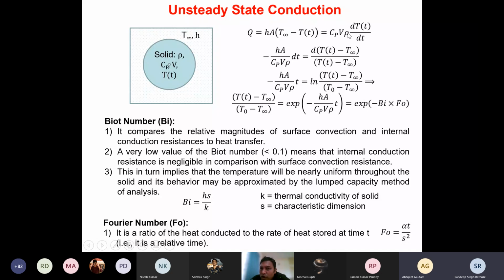Yes. Now what is this dT(t) by dt? Basically we can represent this as the derivative of T(t) minus T infinity, because T infinity being a constant term, if I differentiate that, I will still get dT by dt, isn't it? Yes, sir. So can I put T(t) minus T infinity here? Yes, sir. So that's what we have rearranged here.